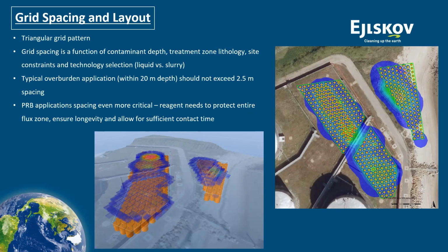And so, especially when you're on developed sites, which most sites we work on are, then now you have a much higher probability of encountering some sort of ground disturbance, whether that's an old soil boring, whether that's a trench, some sort of service line, excavations, and any slight variation in that hydraulic conductivity is going to force that fluid into that disturbed soil.